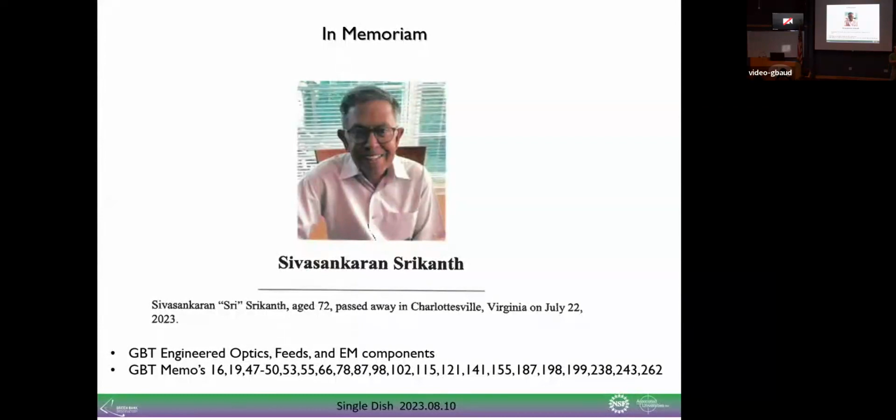We come out with waveguide on higher frequency receivers, for example, and we tie the output waveguide at 50K. The 15K sees stainless steel, which has low thermal conductivity at low temperature, so we do it in stages to get out.